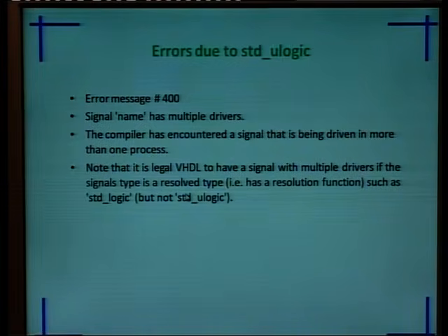If we always use std_logic, our problem of multiple drivers can be solved, but at the same time we may have the problem that our VHDL simulator may take a longer time to simulate, because it is always checking. Even if there is only one input, the simulator will still check the multiple input function, and that will create unnecessary delay, and simulation will take longer. That is why we have to define in our program std_ulogic, meaning one input and one output, or we have multiple inputs and one output.